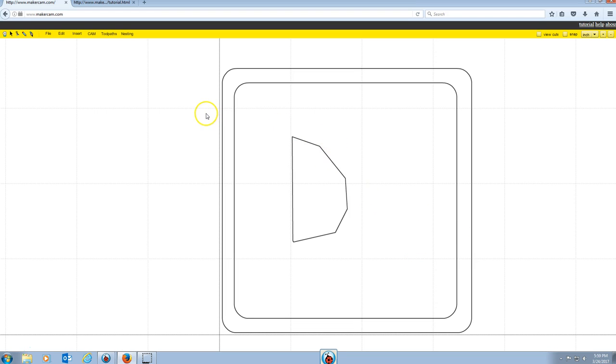But one way that we can select the whole thing, we can try doing it just this way. Actually, that worked pretty well. We can also just drag down across the whole thing and select it. And once we get all the corners connected and it's a complete circle with no gaps, then it becomes one object in the drawing. So we can move it around, and you'll want to take your letter and position it inside the middle of the rectangle.